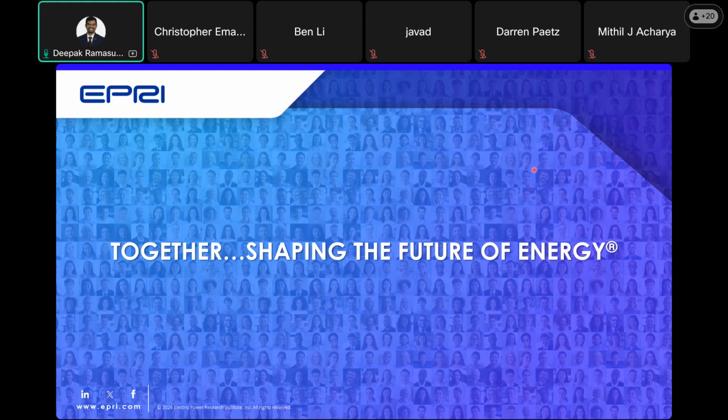Looking at some of the ongoing research work, whether grid forming technology is effective in mitigating these large load based variations is something that's ongoing, because grid forming technology is meant to respond to grid side events in a more natural, grid friendly way, which means that if the load suddenly increases on the grid, it delivers more power to the network.